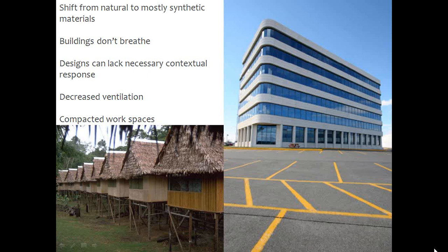Well, the other issue that you can't really tell from this picture on the right is that the intake for the ventilation for the whole building was located near the loading dock where trucks would sit and idle all day, bringing materials in and out of the building. That simply allowed combustion gases to come into the space. So given that we have compacted workspaces inside and these issues we've just mentioned, you can see where the fact that the building materials have added another layer of problem to a problem that existed already to create now a more hazardous indoor environment.